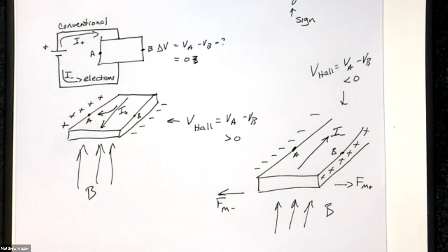All right, if you have positive charges flowing, they're going to flow from positive of the battery to negative, and so you get the accumulation on the left. If you have electrons flowing, they have to flow from negative to positive, and you get the accumulation of charges on the right. And this is easy to do. You take a meter and you poke it on your material and you say, I get a negative voltage. Electrons must be flowing. And that's what happens.